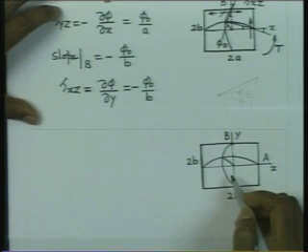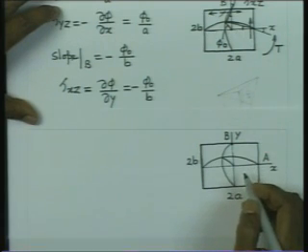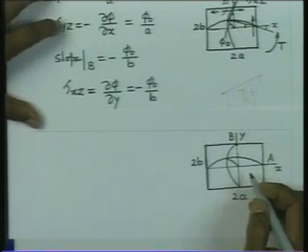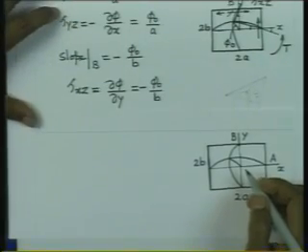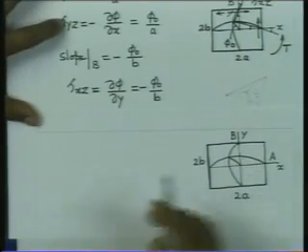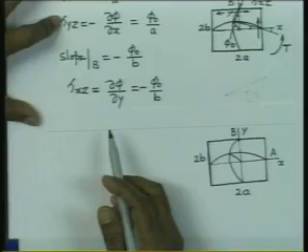It is different from the circular cross section, wherein you have found that the stress is going to be highest at the furthest point. We would like to do a little more calculation to see the value of these stresses in terms of the applied torque.